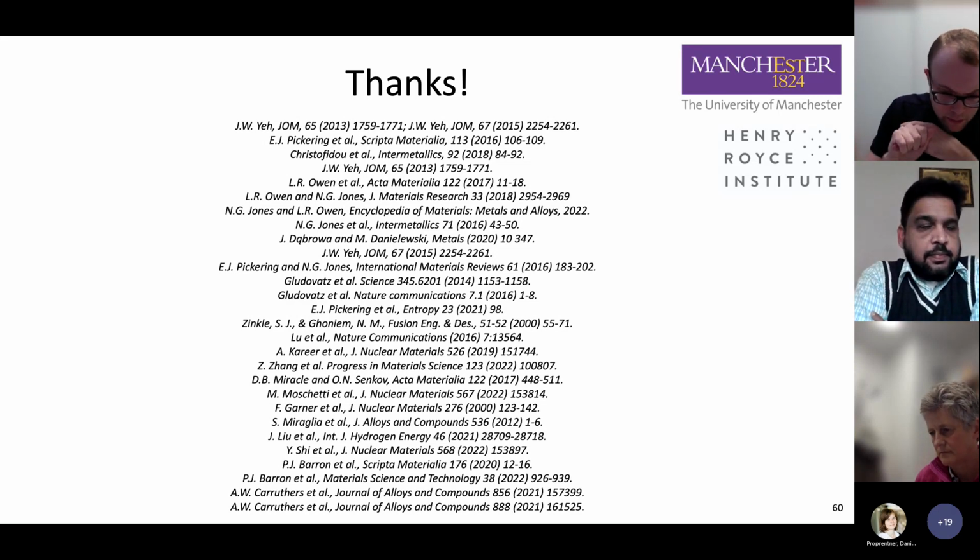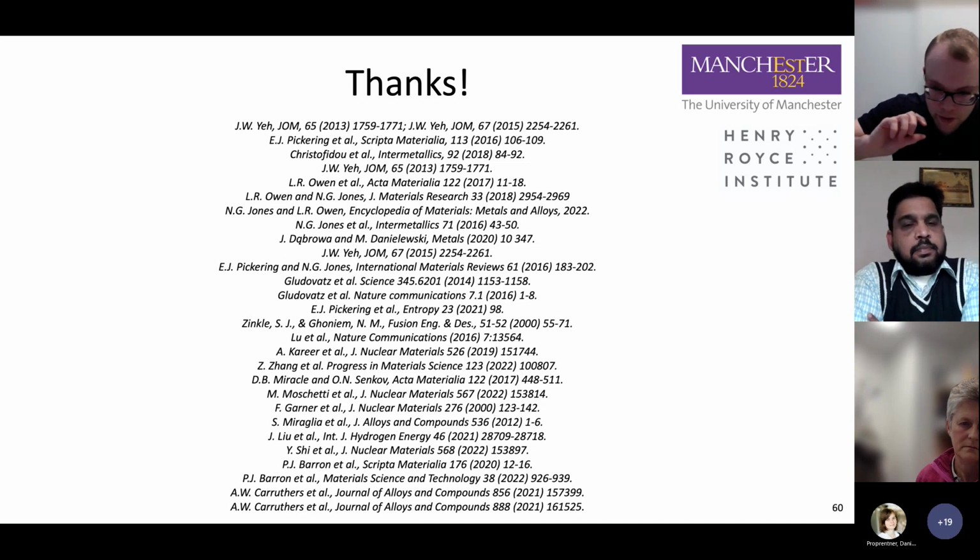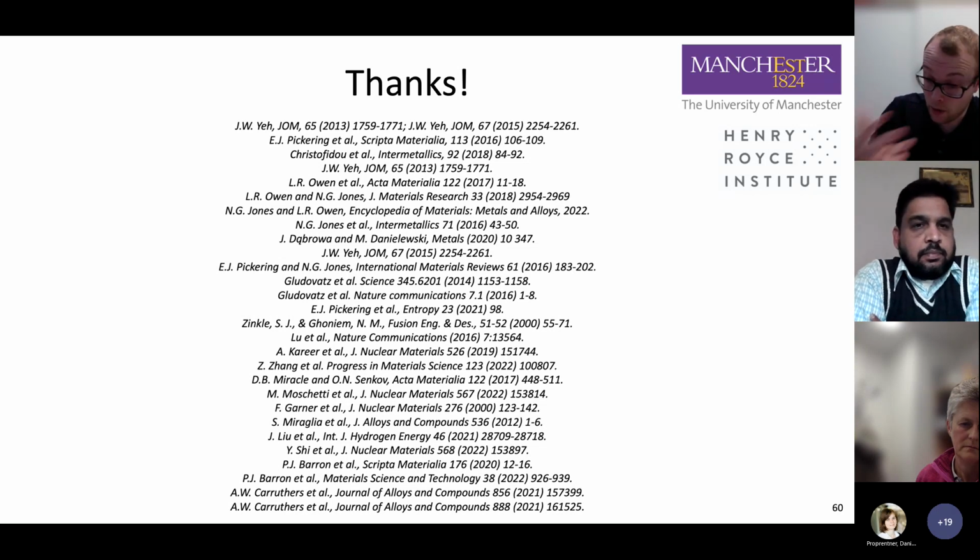The second thing: there's a lot of work that's been done, though I've not done this myself, on the mechanical properties of high-entropy alloys. I showed some graphs at the start of those exceptional cryogenic properties from FCC high-entropy alloys. A lot of that work is based on altering stacking fault energy and introducing martensitic transformations or twinning, and a lot of it has been led by Dirk Raabe in Germany.